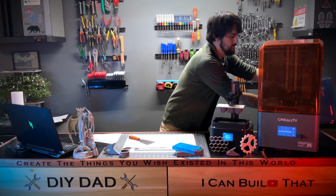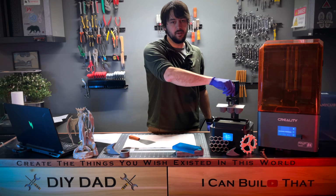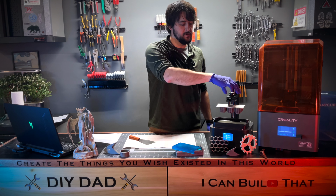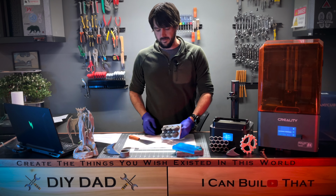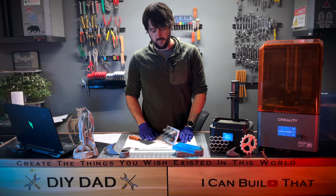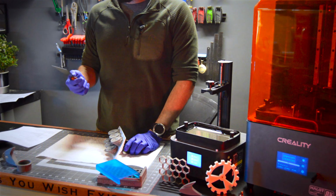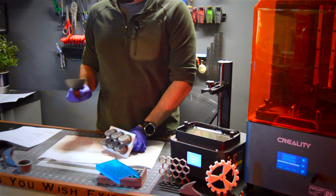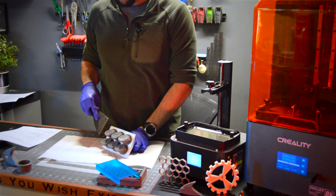This needs to be removed, placed to the side, and you will need to remove your build plate from the printer. Most of these have a single screw where it can be removed and set in a place where you can work on removing the print. At this point, the best tool for the job is going to be a simple scraper. Most printers will come with one of these. However, if not, one can be picked up relatively cheaply.